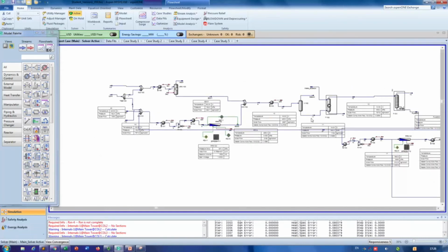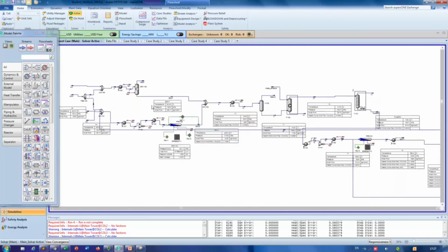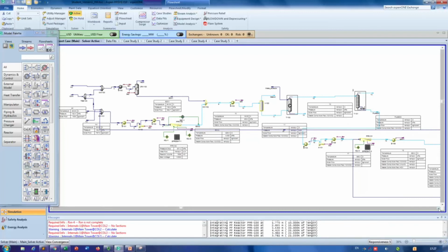We also learned to add a column separator and a liquid extractor, and this one we did as a five-stage liquid extraction. Both are catalytic processes. One we modeled using a conversion reactor, another using a plug flow reactor, and we already know how to add a CSTR and the reaction kinetics and so on. If not, you have to watch lecture 3 or 4.